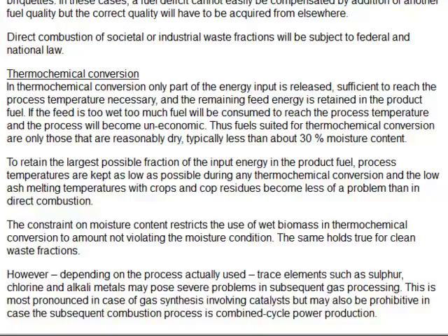So there's a demand in thermochemical conversion that the moisture content of the fuel is low. And when I say low, I mean less than 20%, or at the very least less than 30% moisture content.